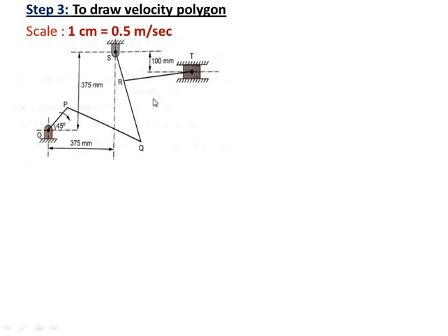So here is the configuration diagram. We have taken it for reference, with which we have to draw the velocity polygon. Now we have to start with a point. Take a point and give the name to the point as whatever the fixed point in a mechanism, say O and S are fixed points. So give O and S to this point. Whatever may be the number of fixed links, there will be 2, 3 or 4 fixed links in the mechanism. All of them will come at the same point OS which we have taken, and with that reference point we have to start with the velocity polygon.